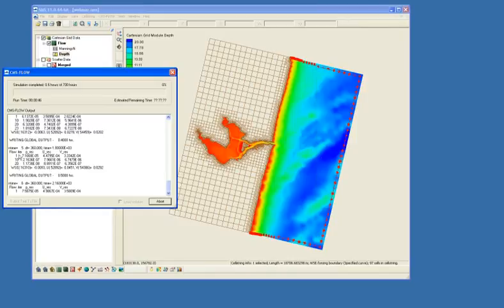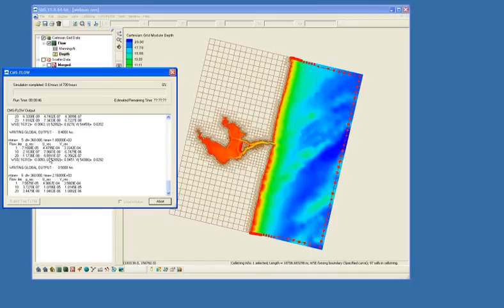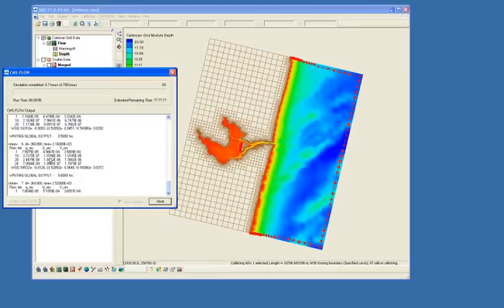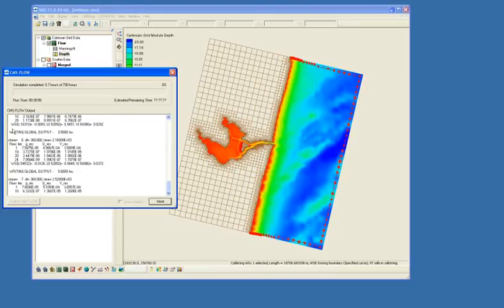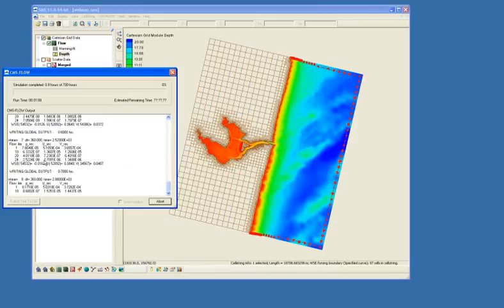You see these iterations are 1, 10, and 20. Basically, like I said, the implicit model goes through several iterations trying to converge on a solution. And so this final number here, 24, 20, whatever it is, was the final one that it actually converged on a solution. There is a maximum number of iterations it will use to converge. I think 40 is the default.